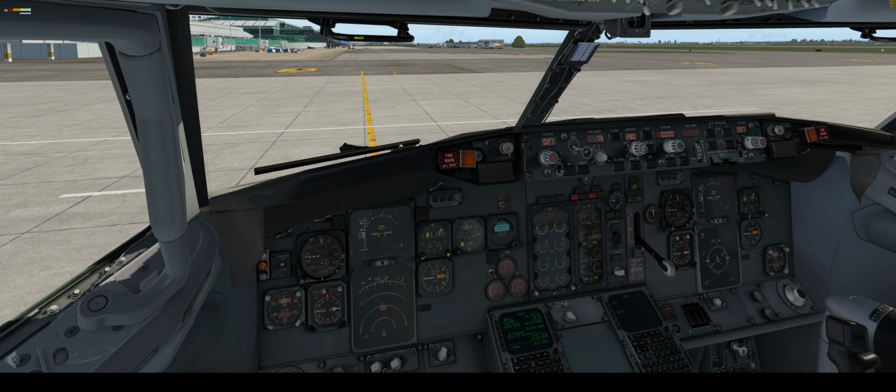I would like to point out, autopilot engagement is 1000 feet above the ground level, so RA, radio altitude. Okay, so 1000 feet. Do not mix it up with NG, it has 400 feet. This has 1000 feet. But basically everything is the same. As I said before, the engine oil and so on, but we are going too deeply into the details, and it doesn't make sense.